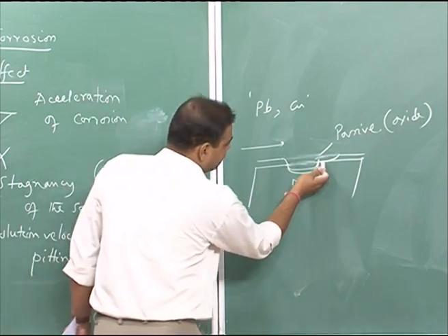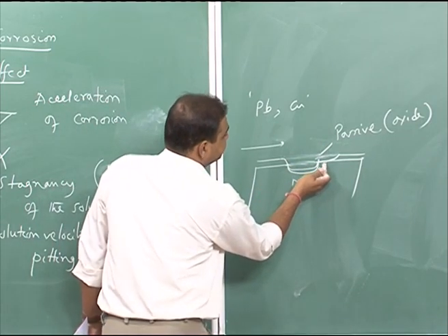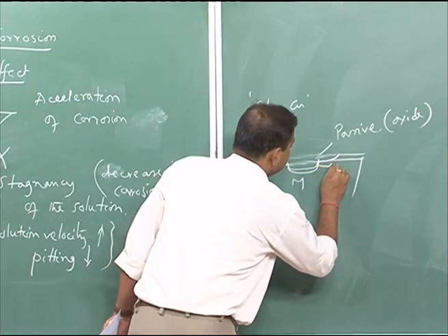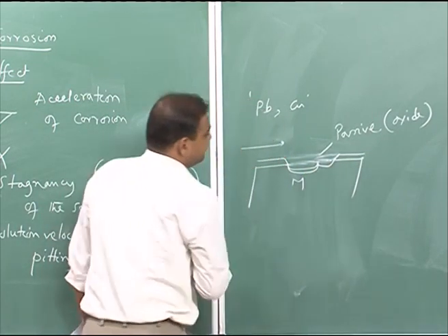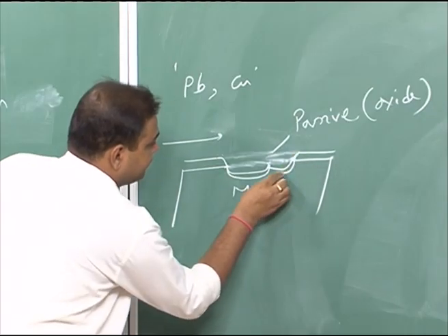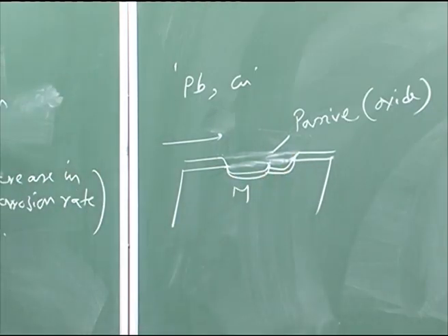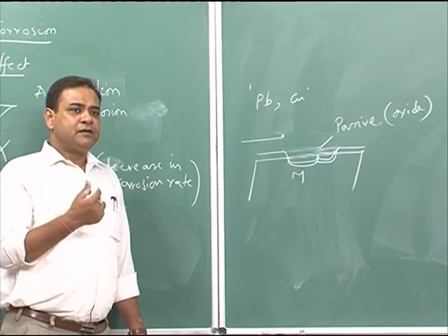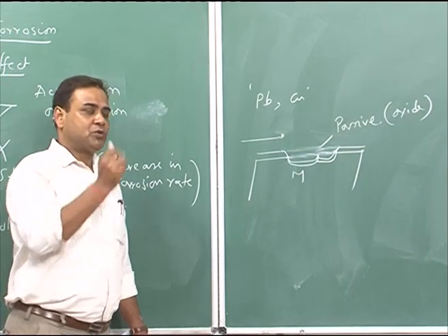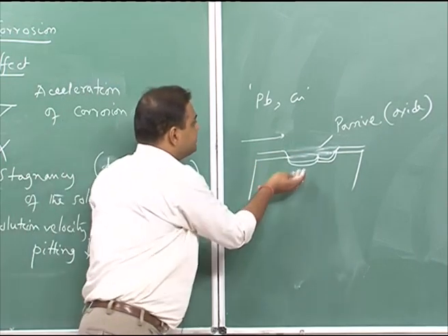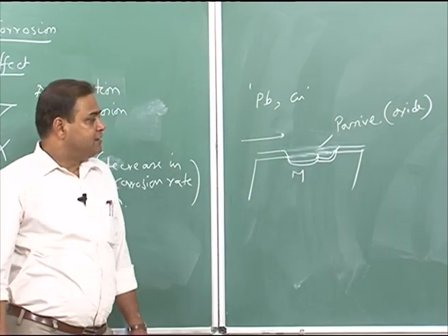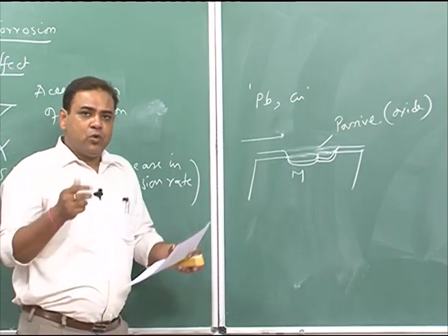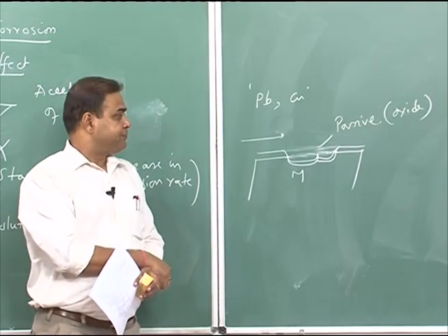So, again the metal surface is exposed to the solution or the corrosive, a little more corrosion happens again, and there would be a formation of passive layer. Before it forms another passive layer, till that period the metal surface is exposed to the corrosive, and at that time the metal dissolution would enhance, and once the passive layer forms, then metal corrosion would be sluggish.